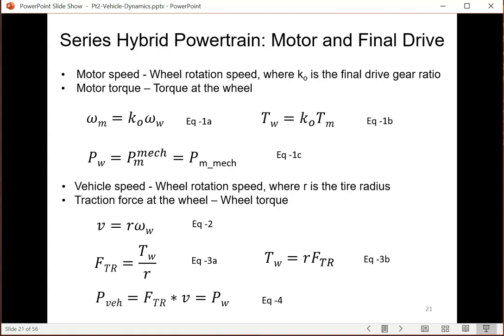That's the total traction effort required to drive the car forward. The traction FTR would be positive in accelerating mode when the motor drives the vehicle. FTR will be negative if you brake, whether through the motor in a reversed working mode or through additional mechanical braking discs, to slow the vehicle down.